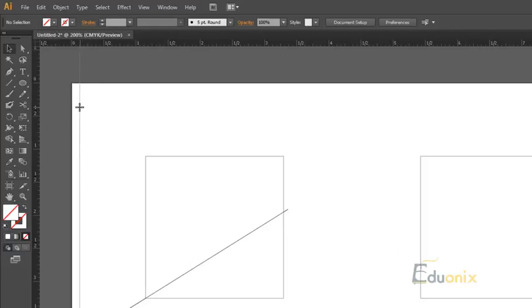So just hold in Shift, and at this point, if you notice, I'm holding in Alt to get the vertical guide because I dragged it from the top, and I'm holding in Shift to lock into the increments of the ruler. And no matter what you set your rulers to, the little increments that appear there, it'll lock into them. So if I wanted 1/8 of an inch, that's perfectly 1/8 of an inch from the origin of my document.